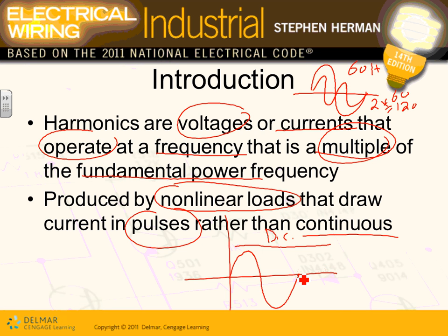Now, when the electronic revolution started to happen, the semiconductors, guys, when they take a signal like this, you know what they do with it? They chew it. They make it look like this. The way they act, the way they react, the way they accept the electrical power, they screw up that signal. Now, to you and I, it doesn't matter, but in the conductors and the transformer, all these rough edges of the signal are heat generated in this equipment. You either have to solve the harmonic problem by having filters, or you have to oversize your equipment so it can handle that heat. Does that make sense? So that's what harmonics is: pulsation.